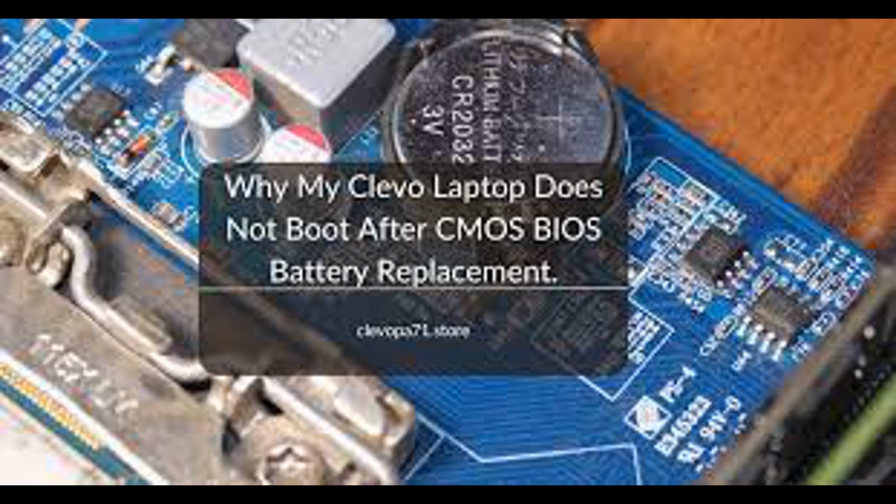Gate oxide. This is the insulating layer between the gate electrode and the channel. It prevents direct electrical contact between the gate and the channel, allowing the gate voltage to control the flow of current without causing a short circuit. Body or substrate. The body or substrate of the MOSFET is the semiconductor material upon which the source, drain, channel, and gate are built.